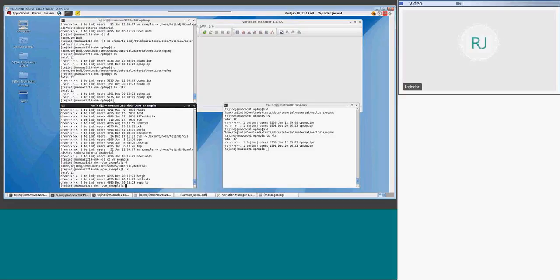Right? But if a design which I verify through Smart Spice, I don't know how you define stable. Functionally it works. Electrically it meets all the electrical parameters. At that stage, can I just go to the Monte Carlo? Yeah, you can. I mean, it's still going to run those under the hood. But you can run the full Monte Carlo. You don't have to run the variability explorer, right? Because you are already at that stage.